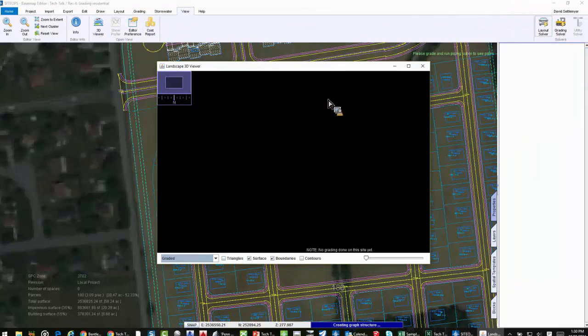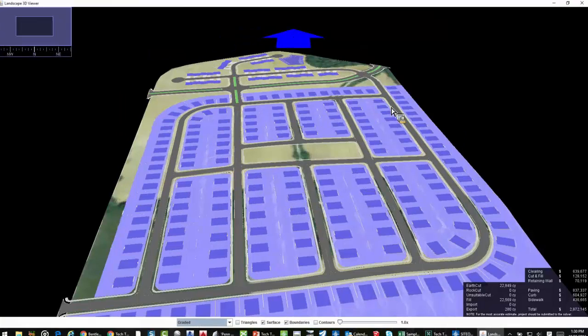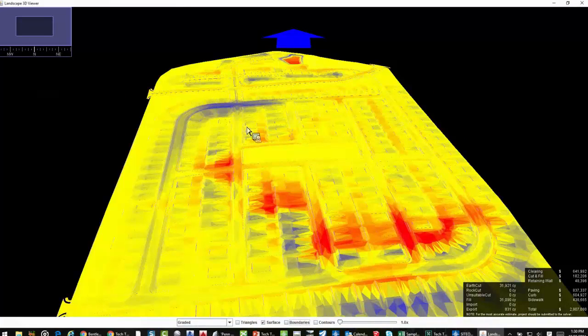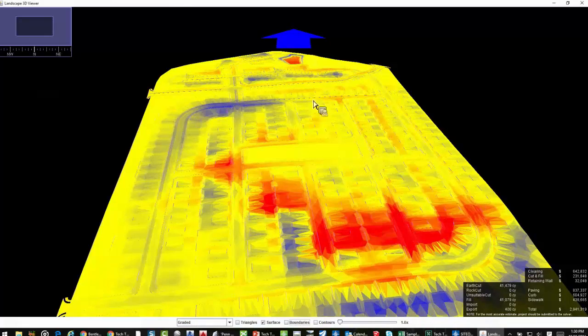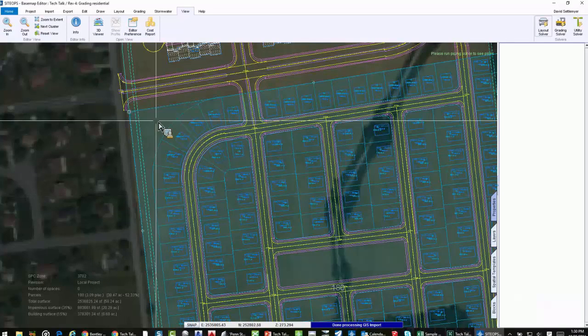And then it actually will start affecting the other roadways that tie to it. So I can then start cascading this issue down through the project. So when we grade, we're actually going to look at grading those areas exactly as we showed. And if you see the little blue right over in that area, that's where we raise the roadway up to have a fill scenario.